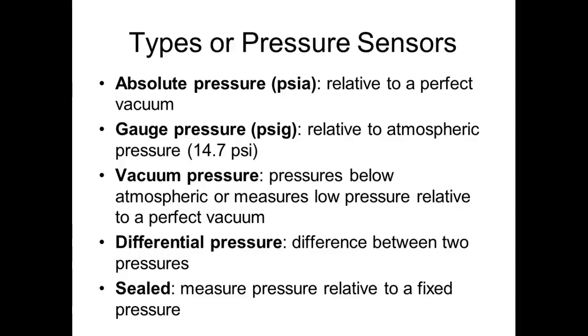So I'm trying to see a difference between the pressure on this pipe and the pressure on that pipe. If you're ever into air conditioning, and you go out and work on a true air conditioning system, you hook your gauges up to the high pressure side and the low pressure side.